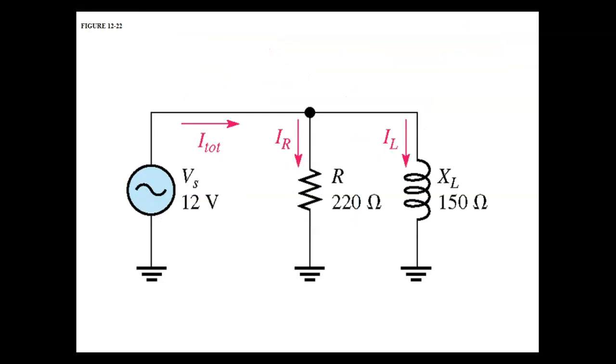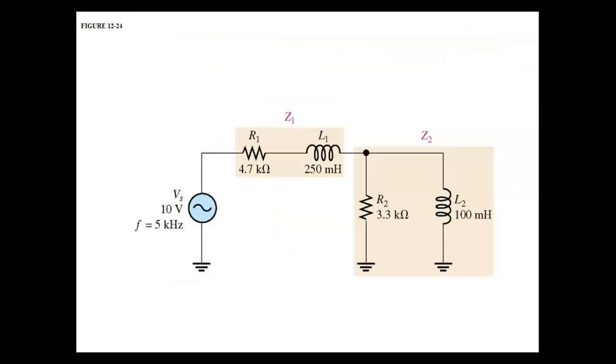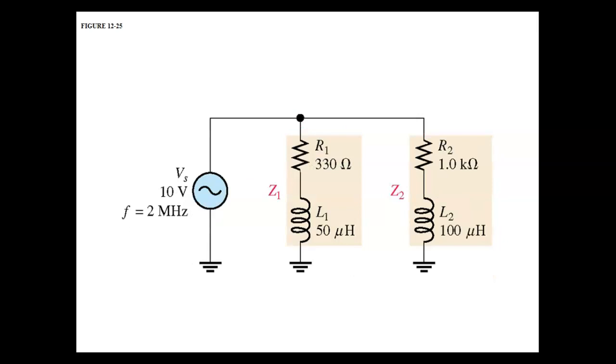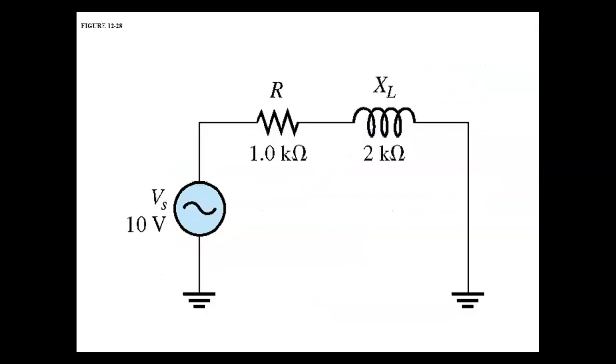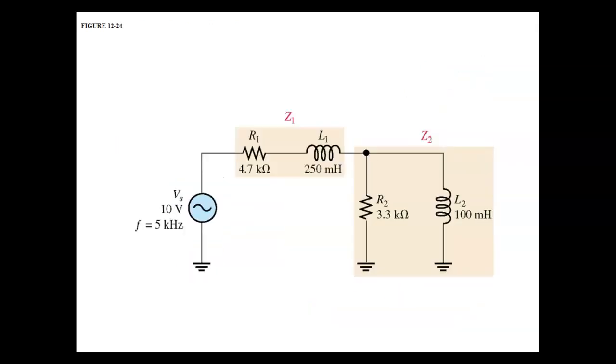So guys, I think this is about it. We're not going to get into these, they get too hard to calculate. And all changes with all RLC circuits are just the formulas. Yeah, and if you get them into ohms, then a lot of the formulas are the same. The only one that really changes is we have X sub C is equal to 1 over 2 pi FC. And then X sub L is equal to 2 pi FL.